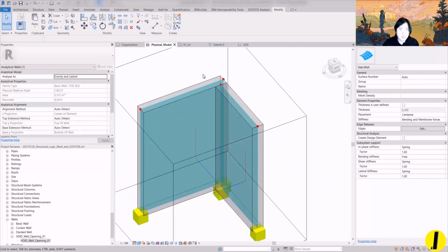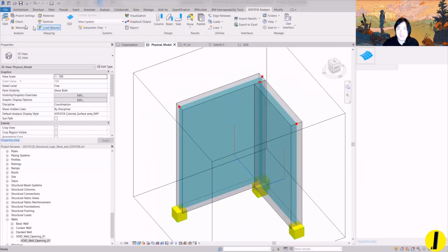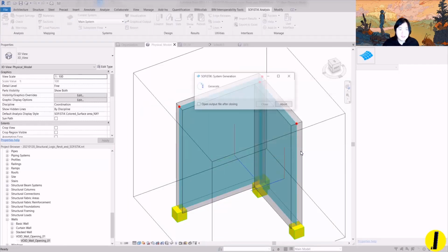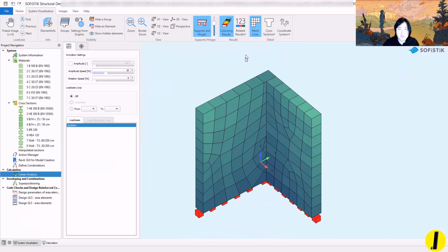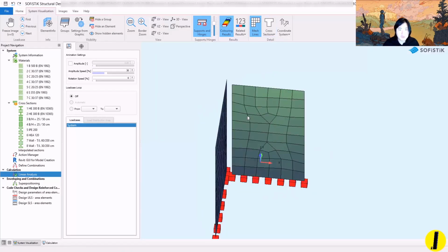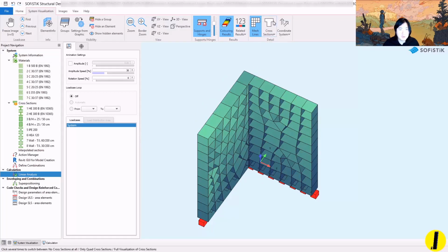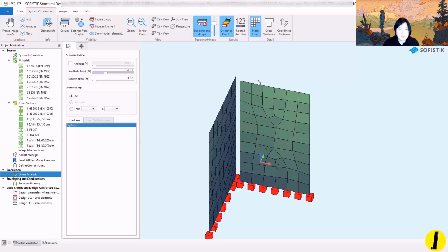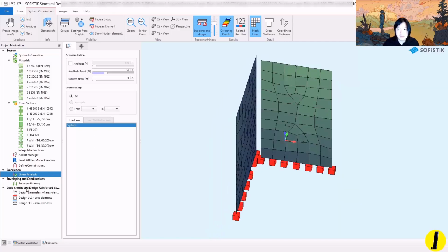So what we can do, if we export now without any settings, let's calculate. Then of course in your calculation model, these walls behave as separate objects. That's what I was assuming. As you can see here, when you give thickness, it looks like the walls are together, but when you hide the thickness of the wall, actually these two are separate walls.